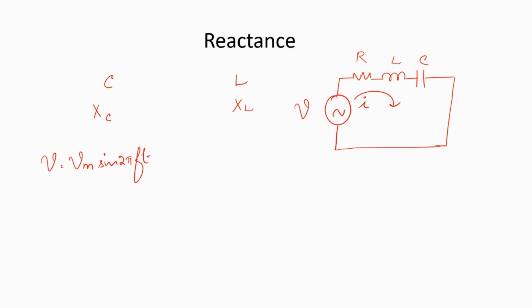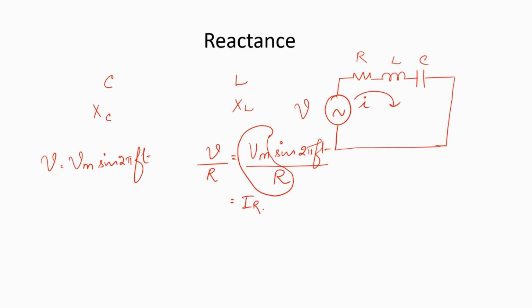When I flows through the resistance, then what would the value of that I be? Right? So, it is just going to be V by R. Or when I replace V with the actual expression, it will be Vm sine 2 pi ft divided by R. So here, the expression for the magnitude of current is Vm by R. Let me call it as IR because this is the current which is flowing through the resistor.